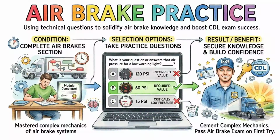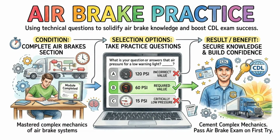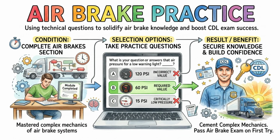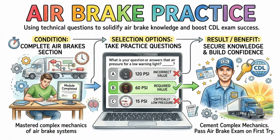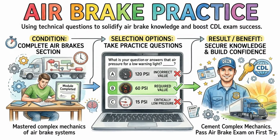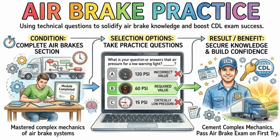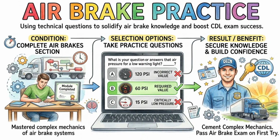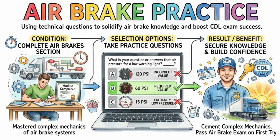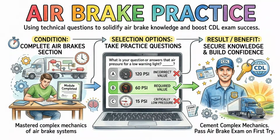To monitor all this air pressure, your dashboard features supply pressure gauges. All commercial vehicles equipped with air brakes must have a gauge connected to the air tank so the driver can actively monitor how much pressure is available. If your vehicle has a dual air brake system, which almost all modern trucks do, you will either have two separate gauges or one gauge with two differently colored needles. It is your professional responsibility to check this gauge frequently while driving to ensure your air supply remains stable.